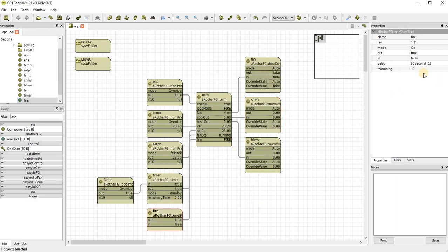So once the fire signal resets, the UCM will start the fan, start its cooling or heating loop as per normal, and everything will resume. So you can manage this by putting a timer after it if you needed to sequence on your systems due to energy requirements rather than turning everything on at once. You could do that after this fire point if you wanted.